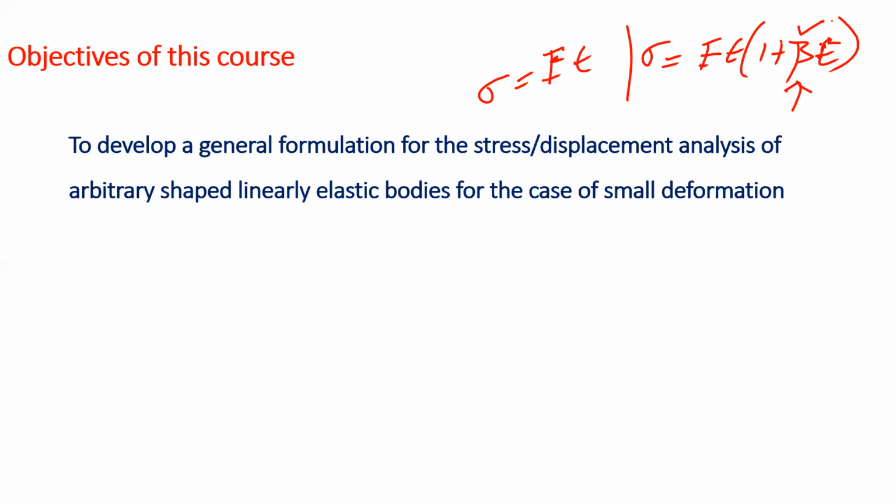This nonlinear parameter will tell us whether a material has accumulated any damage or not. The area is called NDE, non-destructive evaluation. In that, those of you who are interested may want to look at ultrasonics. It is nonlinear ultrasonics. Identifying this parameter is of huge importance to all the design engineers who would want to say whether a gas line is going to break or whether a structure is going to fail in a particular amount of time or not. However, we will restrict ourselves to linear cases.